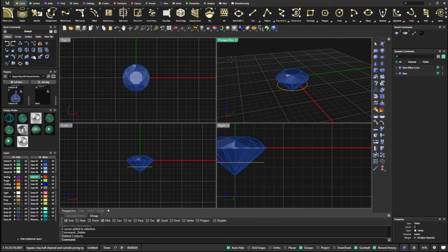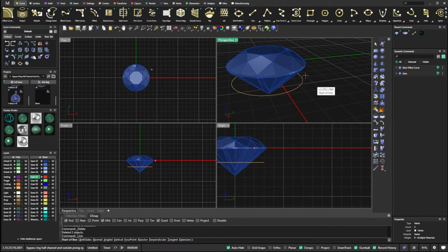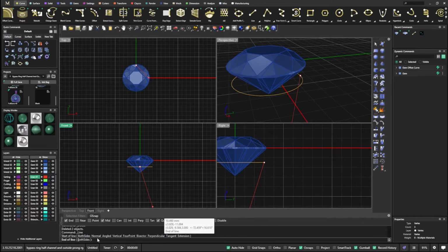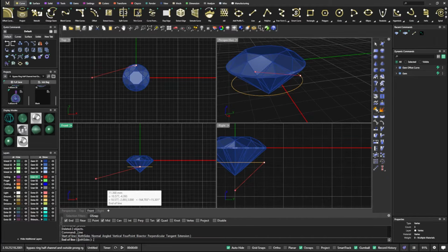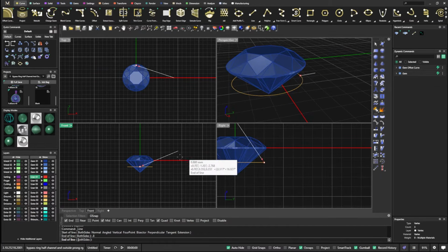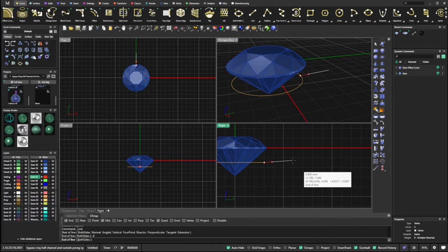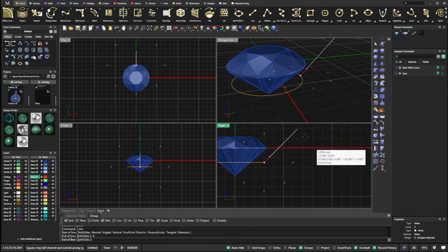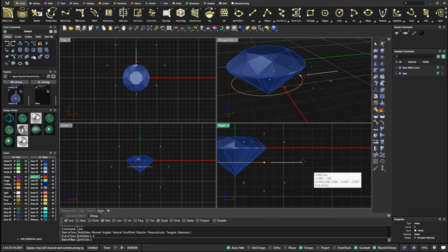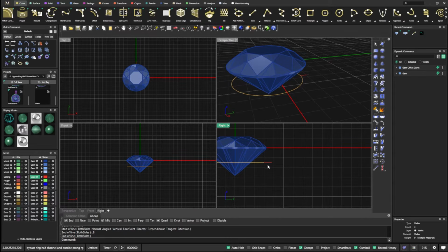So let's right click here and bring back that line curve, and we'll snap to that quad, and then we'll come down here and say we want it at a 0.8, right? And now it's locked into that 0.8. I'll hold down shift so it's straight out. I can go 45 or 90, and I'll snap it in there.